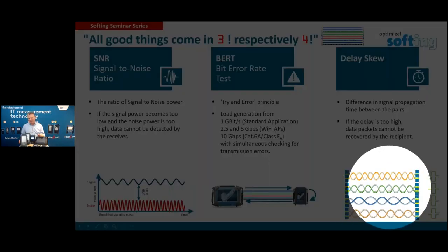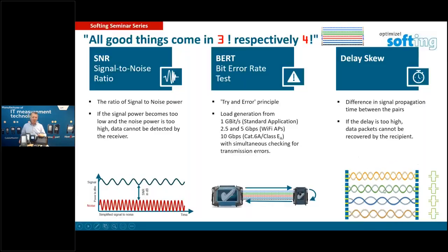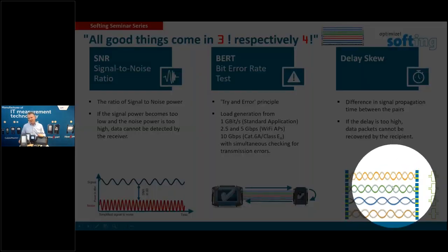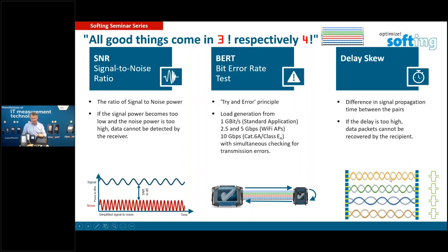This is in fact a more important point for unshielded twisted pair cable, because unshielded twisted pair cables have different strandings on the twist. Here in Germany, and I believe in Central Europe, we mainly use S/FTP cables, so that means pairwise screened cables. So this is not an important one here, so you will not so often get a fail on delay skew if you're using pairwise shielded twisted pair cables.